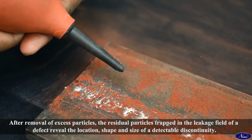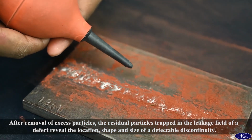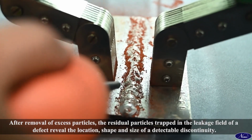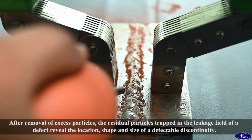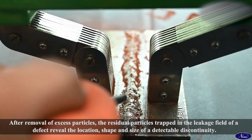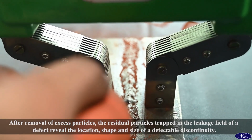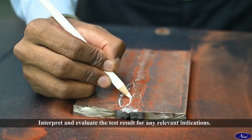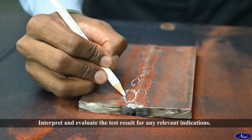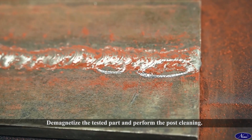After removal of excess particles, the residual particles trapped in the leakage field of a defect reveal the location, shape, and size of a detectable discontinuity. Interpret and evaluate the test result for any relevant indication. Demagnetize the tested part and perform the post-cleaning.